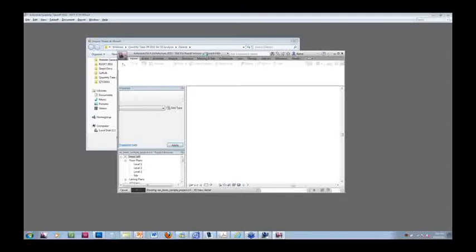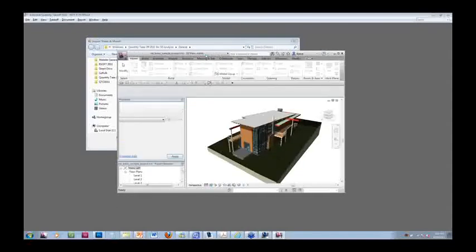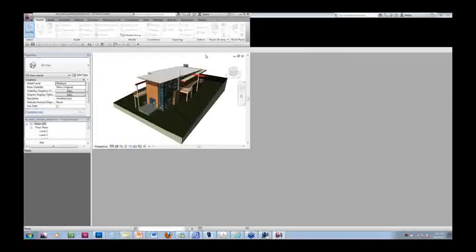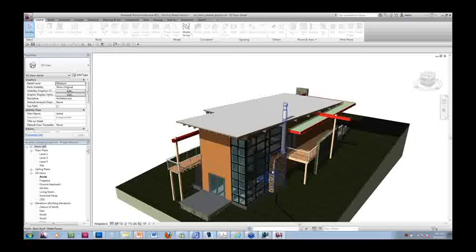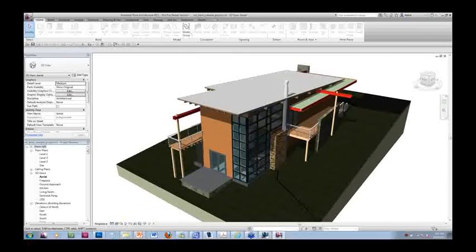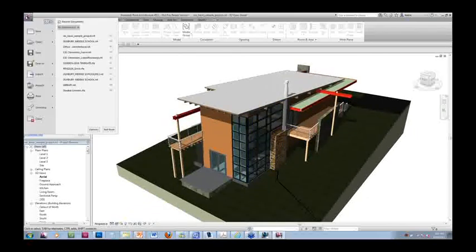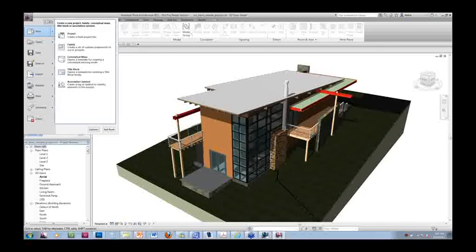Now, it's the same technique that you can apply to pretty much any other BIM application that you have available. It could be MicroStation from Bentley. It could be ArchiCAD, Vectorworks, etc. Now, you can export this, and because it's Revit, I'm going to use the native format, which is a DWF. Like I said, you can also bring in DWGs from a CAD file that is exported out of AutoCAD, that's AutoCAD native format, or from another application that exports to that.